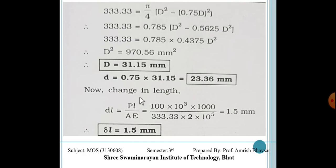Now the equation for change in length, delta L, is equal to PL upon AE. So P is equal to 100 into 10 raised to 3, length is equal to 1000, divided by the area we have, and E is equal to 2 into 10 raised to 5. So delta L is equal to 1.5 mm from this equation.